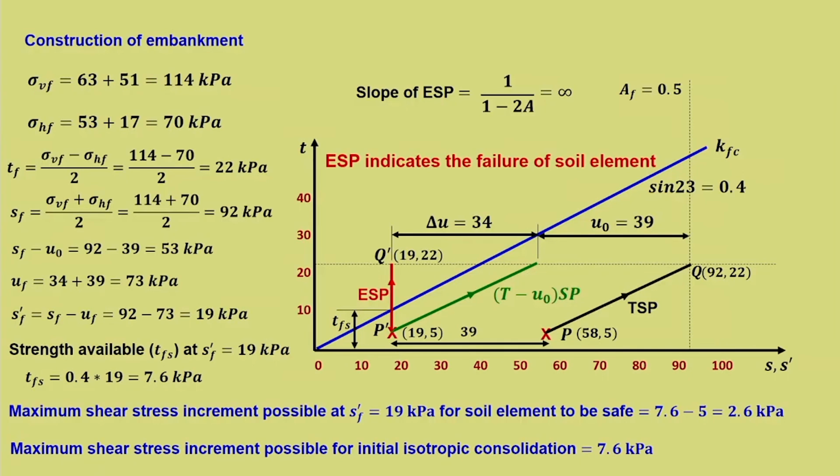It is only added information which we can get from the stress path plot. For example, if the starting point is again towards the left, we will have even less allowance, or if this point is slightly here, then we have this much strength available. So, that much amount of embankment construction is possible. So, this particular plot helps us with various possibilities and understanding related to a given field condition. This is what we have discussed related to the embankment. Now, this can be any problem, it can be a foundation, it can be retaining walls like the one we have discussed in the last lecture.